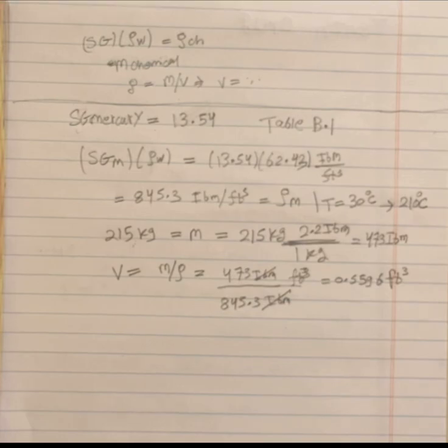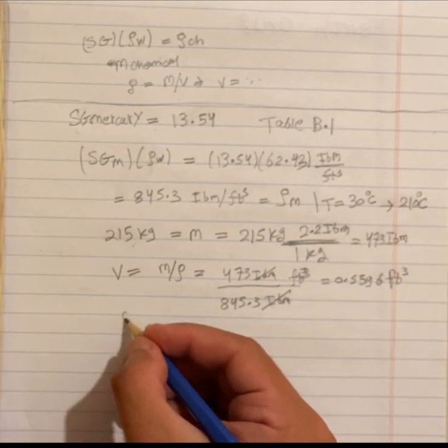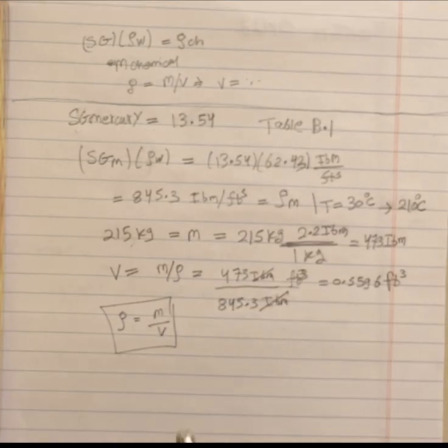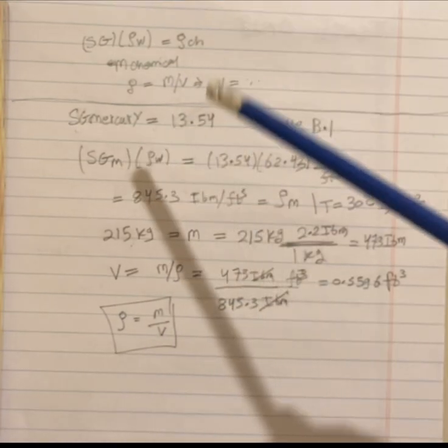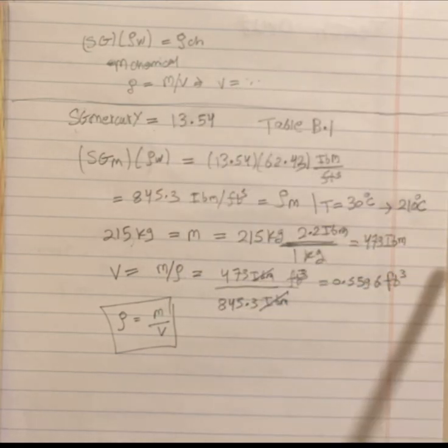You would just understand that increasing the temperature will not have an effect on the mass, and the density is slightly changing with temperature, which means if the density and the mass are constant, it means that the volume is also constant. It means that density equal to m over v will not change. This is the case when you have liquid. So you don't need to repeat the calculations here. What you found, I'm not saying exactly, but I'm saying is close enough to what you will find if you do the calculations again at T equal to 210.